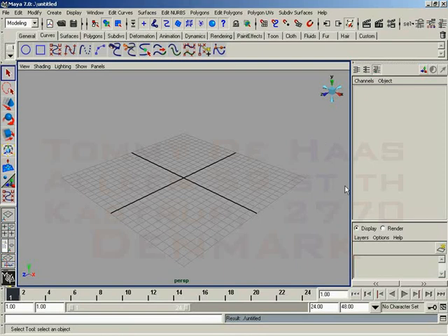The bevel command will, as the name suggests, create a beveled surface using a profile curve. Now, it's an older command. It's probably not one that you'll find yourself using a great deal. It has, for all intents and purposes, been replaced by the Bevel Plus command, which we'll be talking about a little bit later.